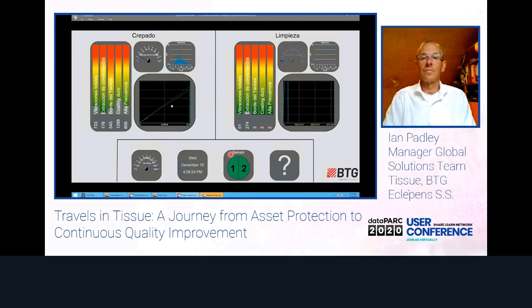Here we have the blade damage indicator, which tracks the vibration increase through the blade life. The current blade is the bright line growing from the bottom, and dimmer lines show the previous two blades for comparison. Underneath, we show the current machine speed, and on the right-hand side of the screen we monitor the cleaning doctor. In this example, the cleaning blade is not in use. Now for a demonstration. Everything looks okay right now, but let's see what has happened in the last 48 hours.